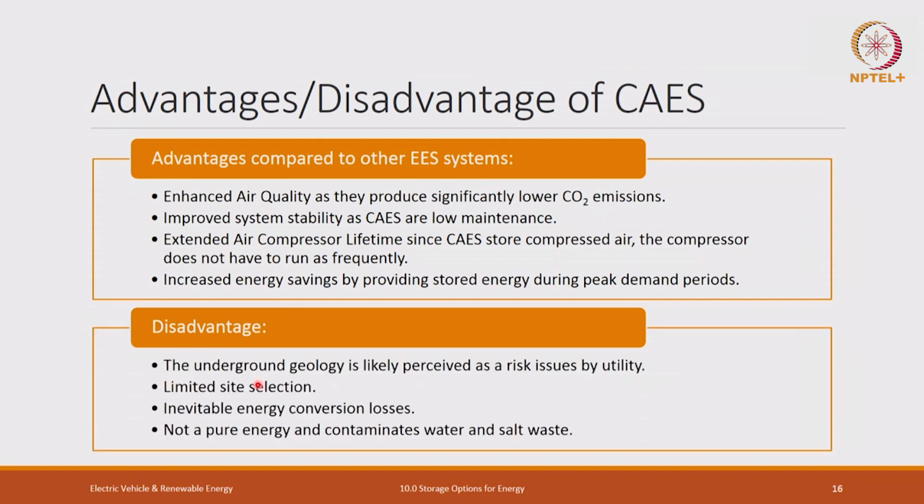The disadvantage: you don't know what is underneath or in that particular cave. You cannot select any site. You have to find wherever this criteria is met, where you have hard rock, where you have an already formed cave. Otherwise, if you are going to make it, then it's going to be a very costly affair. Energy conversion loss is quite high in this process. So that's why round trip efficiency comes down to a maximum of 60%. And that's not a very good option.